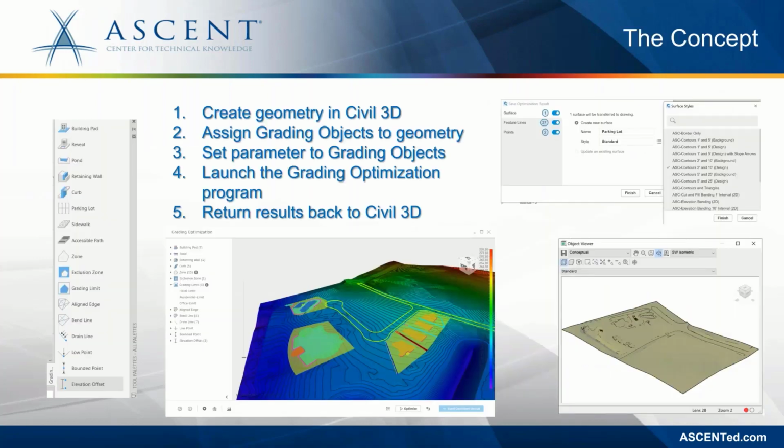Okay, so the concept of grading optimization is that you create your geometry in Civil 3D. They can be regular AutoCAD objects, or they can be Civil 3D feature lines or points. And a variety of objects require a point. Some grading objects require a linear element, and some require a closed polyline or feature line. Once the geometry is created, we attach grading objects to that geometry, and then we set the parameters of those grading objects within Civil 3D. Then we launch the grading optimization program, and as I said, that's a separate window altogether that can be moved to a separate screen, or minimized, so that you can continue to work in Civil 3D.